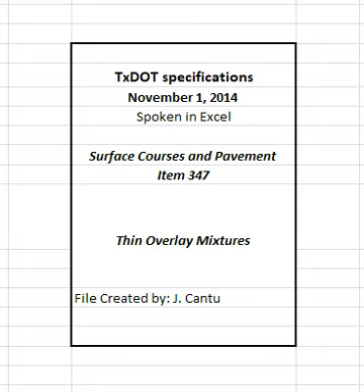Evaluate areas with severe thermal segregation by performing water flow testing in accordance to TxDOT 246F and verify the water flow is greater than 120 seconds. Remove and replace the material in any areas that have both severe thermal segregation and a failing result for water flow test unless otherwise directed. 4.7.3.2 Windrow operations. Operate windrow pickup equipment so that when hot mix is placed in windrows, substantially all the mixture deposited on the roadbed is picked up and loaded into the paver.